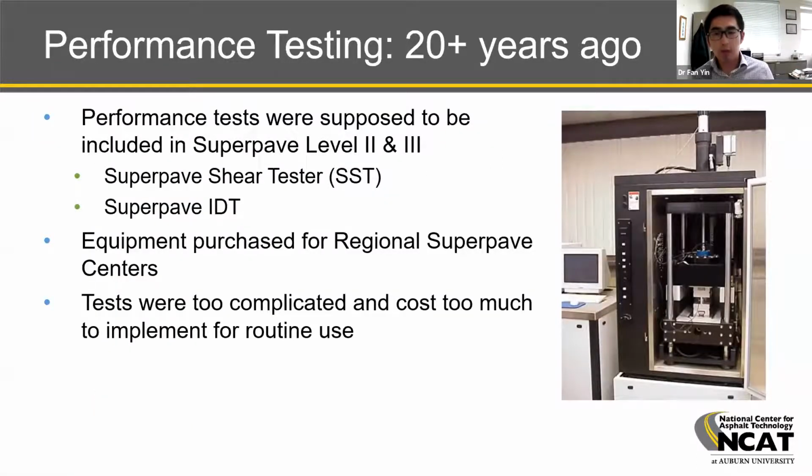When Superpave first came out about 25 years ago, at least in the US, performance tests were proposed as part of the volumetric mix design framework, at least for the level 2 and level 3 design methodologies. The researchers at that time proposed the Superpave shear tester to look at rutting and fatigue cracking, and the Superpave IDT test to look at thermal cracking, or low temperature cracking resistance.